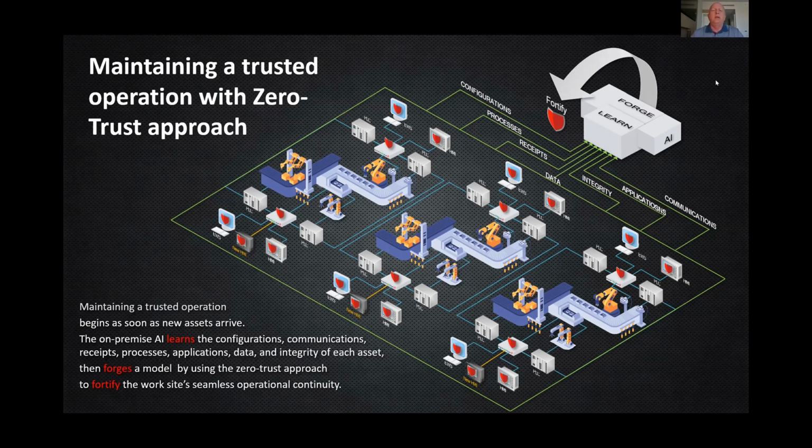We talk about installing agents, understanding that it is a sensitive issue, but going back to the ability to protect what we can protect with an agent-based either real-time scanning or application control, and then moving to the network layer for the additional controls. So doing intrusion prevention at the network layer, doing application and protocol control. So who can talk to who, and even down to the protocol level, what can this protocol pass to the PLC? Can it read only? Can it write? Can it modify? So we can actually get down to that level. And if we can get down to that level, we can then create that network segmentation between either the station, the zones, or even for the entire shop floor, getting down to each individual station within the shop floor.